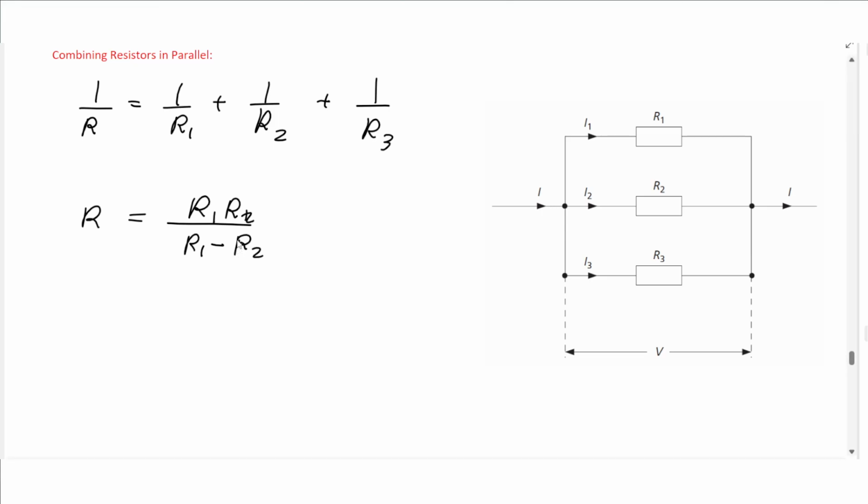Just a reminder, when calculating using the original equation 1 over the total resistance, at the end of your calculation you must calculate the reciprocal. So you calculate 1 over something plus 1 over something and so on. After you finish and you press equal, you must press 1 divided by answer, or answer to the power of -1, to get the reciprocal.